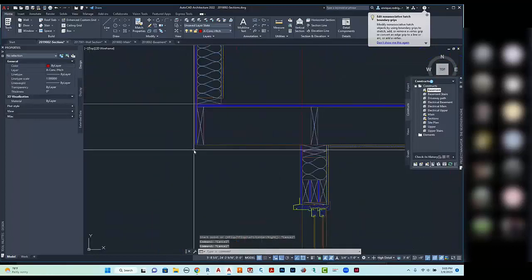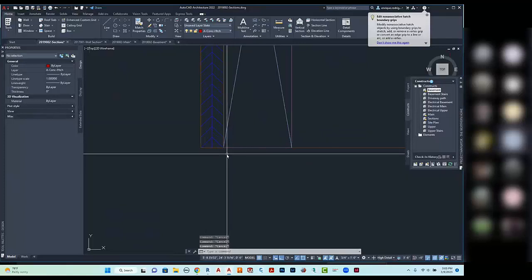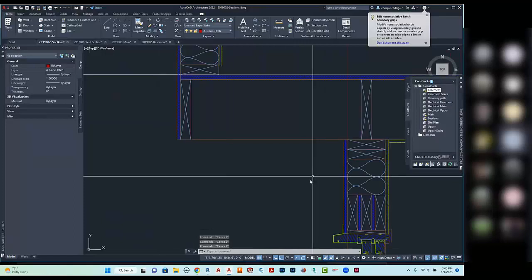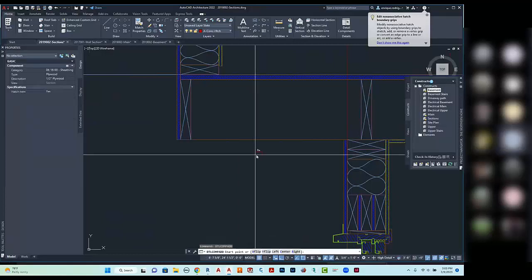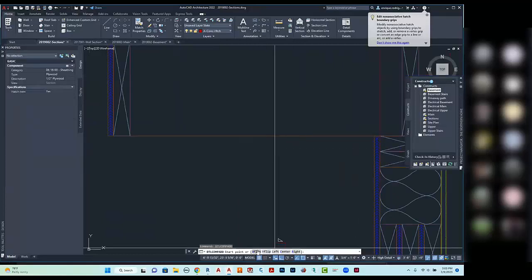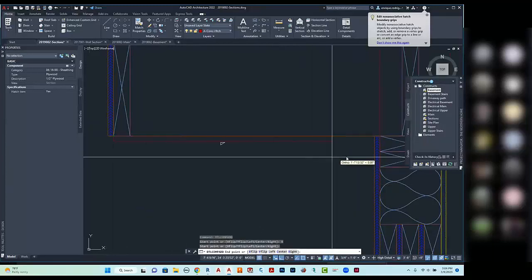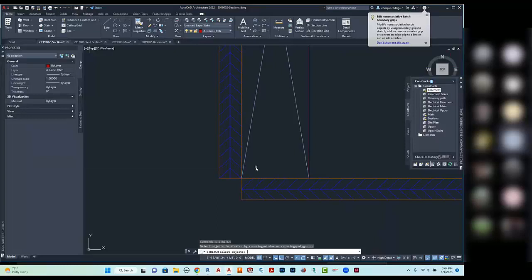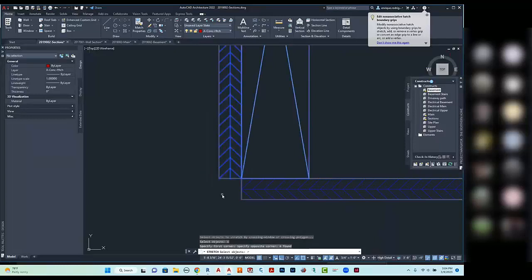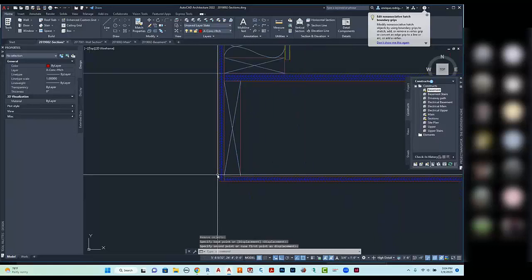to this point. I probably want this to overlap the joint that's coming horizontal at this point, but I'm going to go ahead and draw the horizontal one first. Repeat detail component should repeat itself. So there is my 1/2 inch plywood. At that point, now I'm going to go ahead and stretch this. R for remove. I'm going to remove this and that, and I'll stretch this guy down to here.